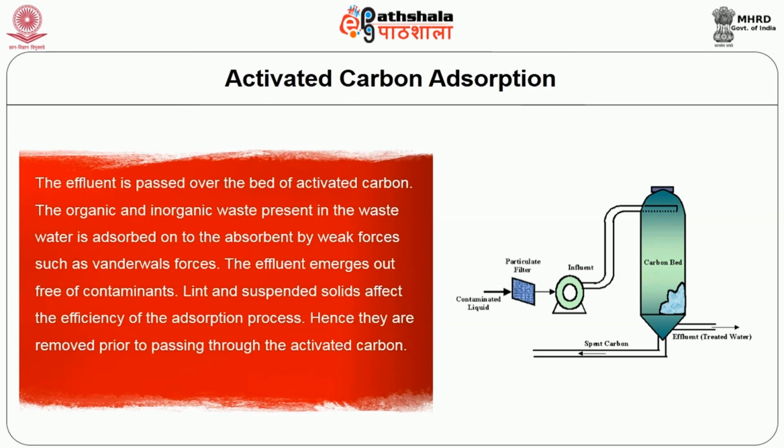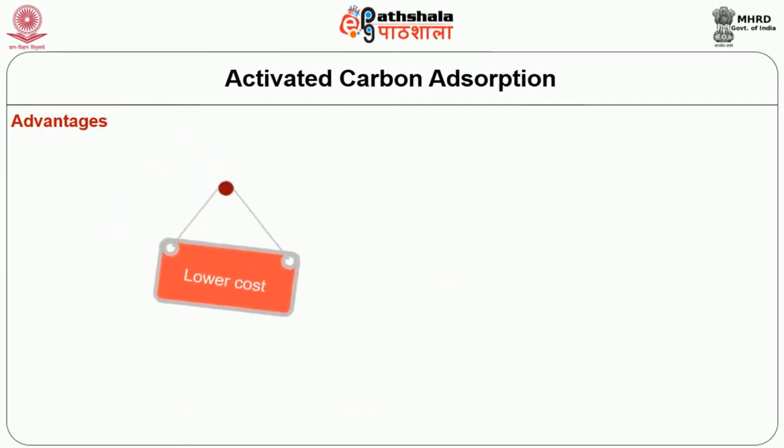The organic and inorganic waste present in the wastewater is adsorbed onto the adsorbent by weak forces such as van der Waals forces. The effluent emerges out free of contaminants. Lint and suspended solids affect the efficiency of adsorption process. Hence, they have to be removed prior to passing through the activated carbon. Advantages: lower cost and simplicity in operation.